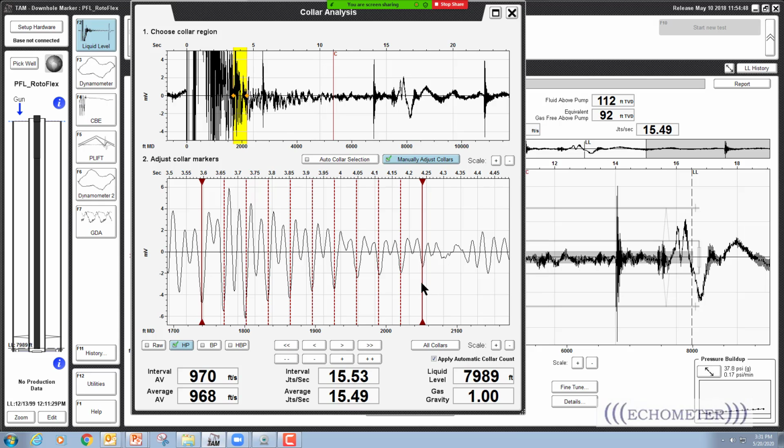Okay. Well, linking the next question with the implosions, what is the minimum casing pressure required for an implosion shot? There's not really a minimum pressure because the gun has to open to make an implosion shot. So as long as you can open the gun and the pressure on the outside of the gun in the well is higher than the pressure on the inside, it'll create a traveling wave. So I don't really see there's a limit, but if the well is shallow, we may want to do a tiny implosion shot. If the fluid level is high, we may want to do a tiny fluid level shot.